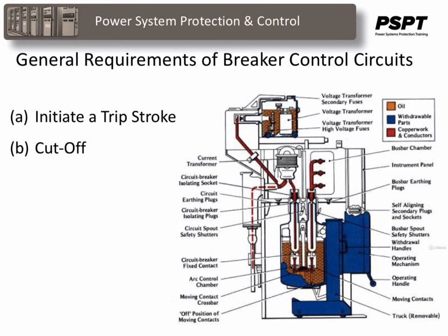There could be an auto reclose coming close on the heels of the trip signal, and if the control mechanism to trip the breaker is manually operated by an operator, chances are he's going to hold that trip signal in a little bit longer than is required and could cause the breaker to trip again if it was automatically reclosed. So anyway, once a trip signal is sent to the trip coil, there's a cutoff that automatically disconnects the trip coil from the initial trip being sent.